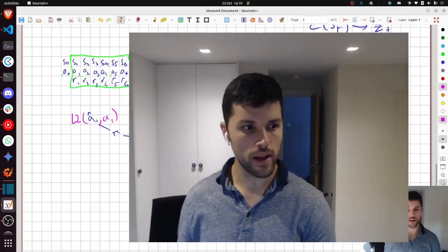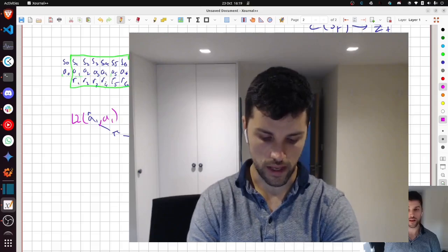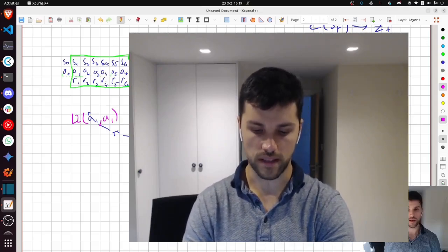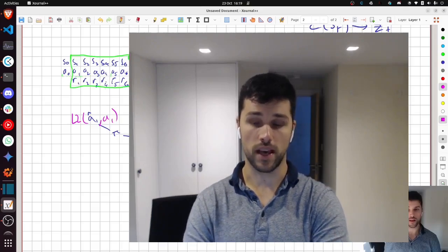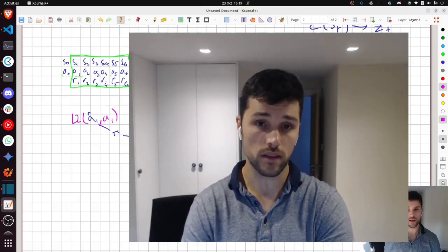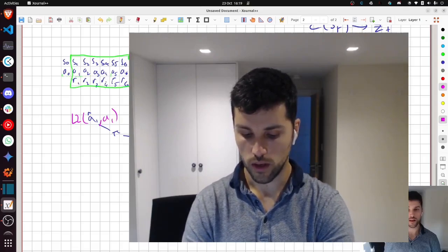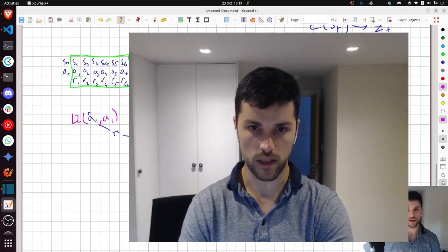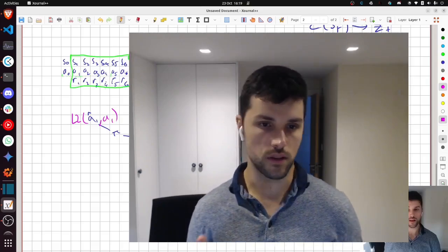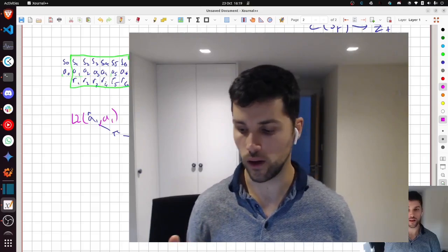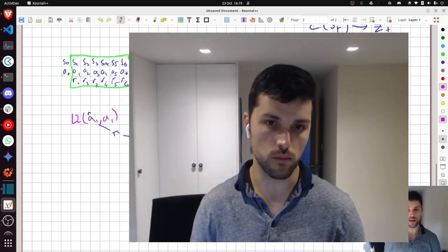When we're doing rollouts with this robot, remember we're doing rollouts with the MPC, and MPC relies on sampling from a Gaussian distribution, and there's noise when you do that. So you won't necessarily get the optimal sequence of actions. This is important. It's part of the exploration versus exploitation dilemma of RL. We inject this noise on purpose so that we can do more exploration.